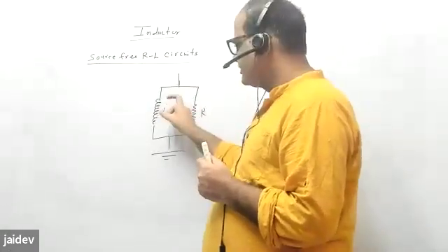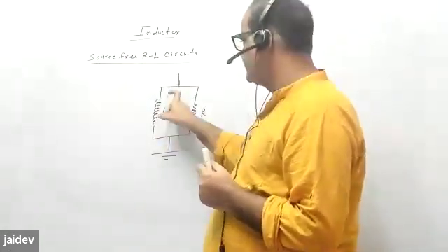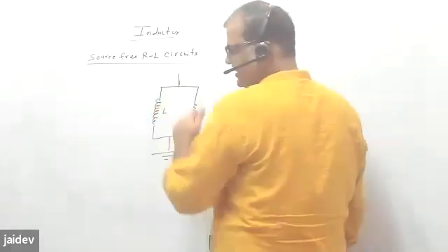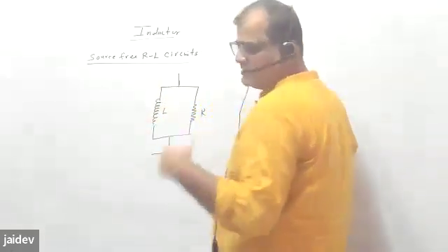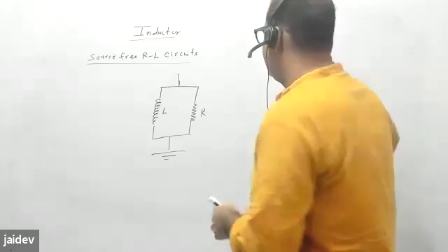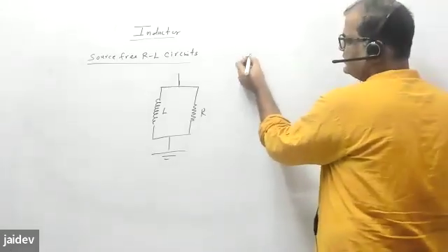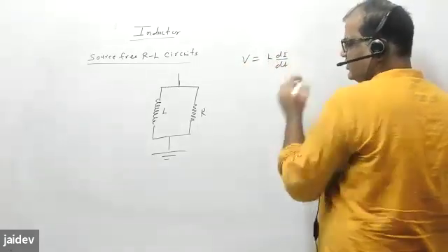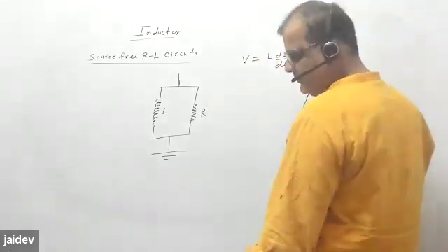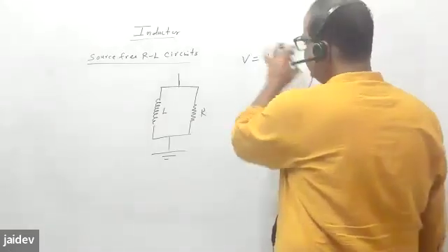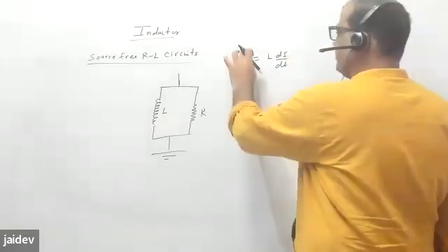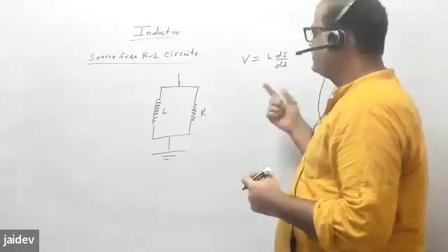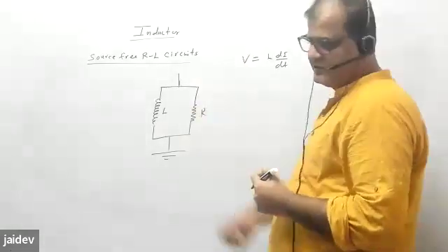Current will remain here, so voltage will also be there, because there is always a change in the current, and we know the voltage across the inductor is given by L di by dt. The current is slowly reducing, so there is a di by dt component, so there will always be some voltage. Of course, as the rate is decreasing, the voltage will also be decreasing.